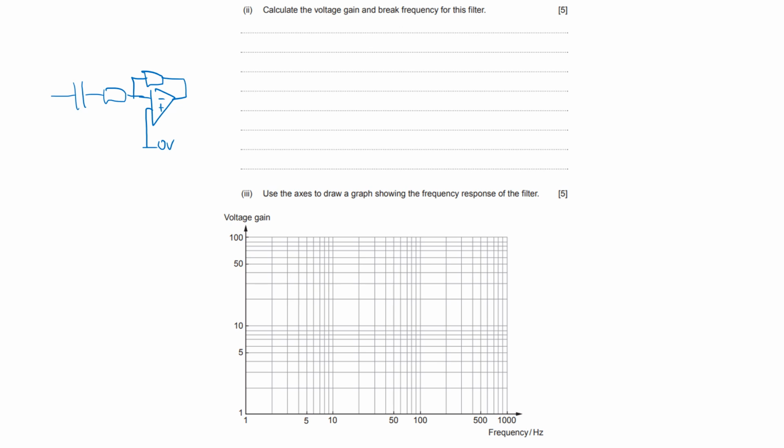It's a treble cut. You put a capacitor in parallel with the input resistor. It will be a treble boost. Okay, but try and just learn them. That should be okay.